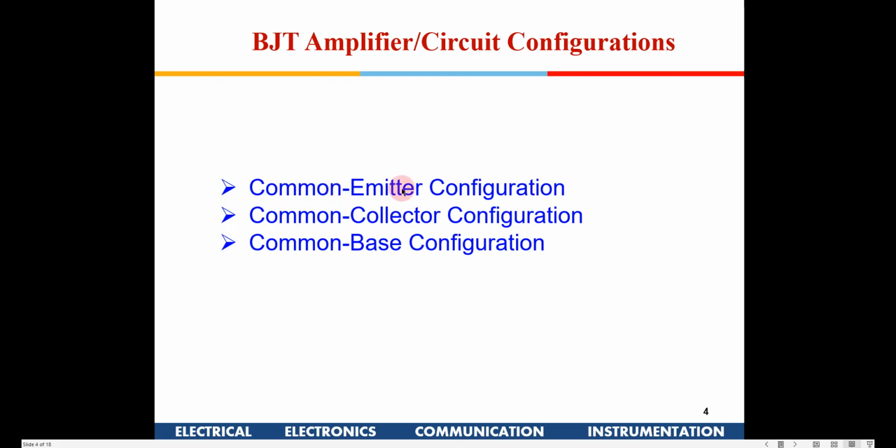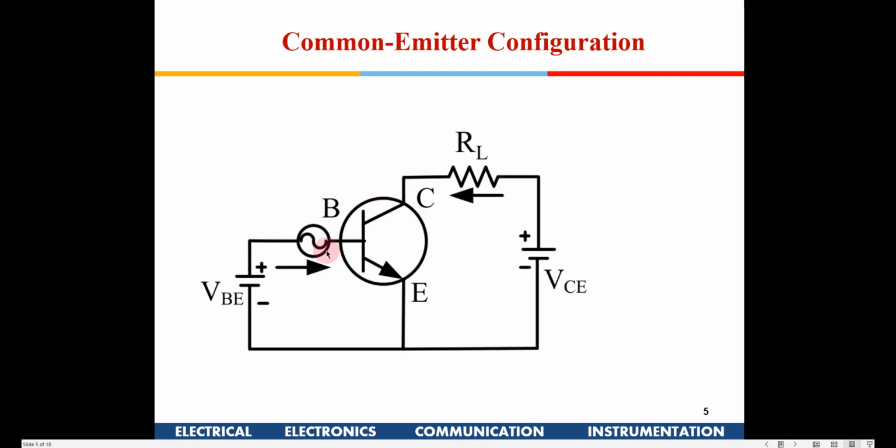Okay. So there are several amplifier configurations. The first and foremost, which we are going to learn today, is the common emitter configuration, right? In the common emitter, the emitter is common to the input signal and the output signal. This is the common ground here. So you are biasing this transistor with a base voltage. This is required so that this transistor is not in the cutoff region, but is more than 0.75 V, so that when you are applying a few millivolt signal, it still remains on for the entire AC signal, right?